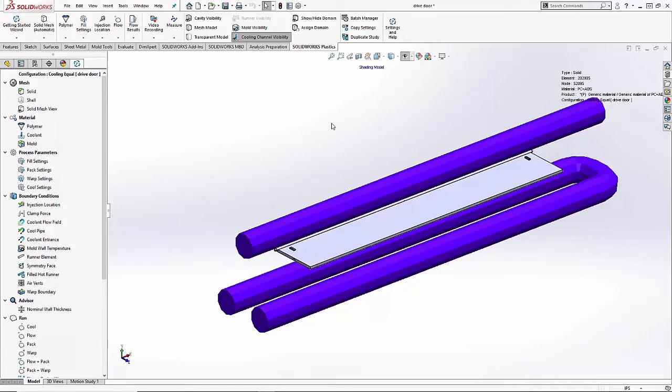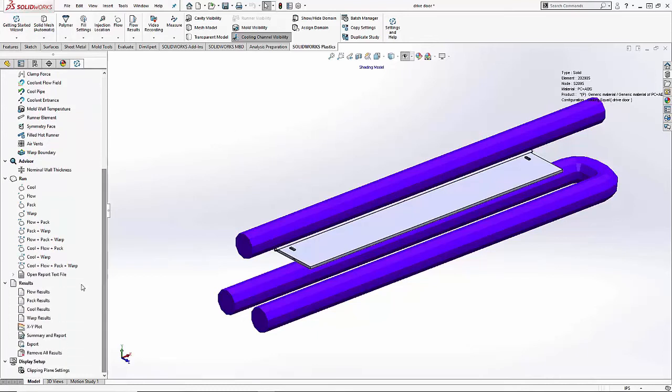Some mold designs may have water lines that zigzag back and forth across the cavity. As they do this, they're also pulling heat from the injection molded part and getting hotter as they go through. So if you have multiple cavities, one cavity may have more heat on one side than the other, or you may have more heat on the A side or the B side. Our simulation software has the ability to simulate this as well. When we set it up, we're able to create our water lines off of 2D sketches, or we can also model the water lines in 3D.